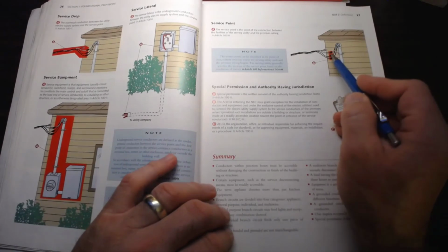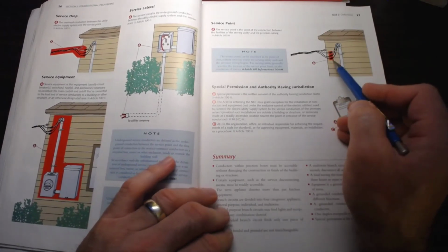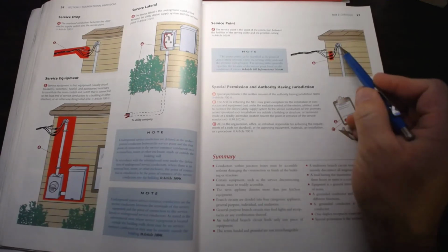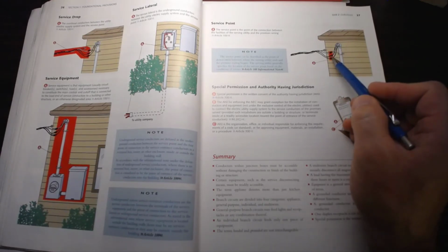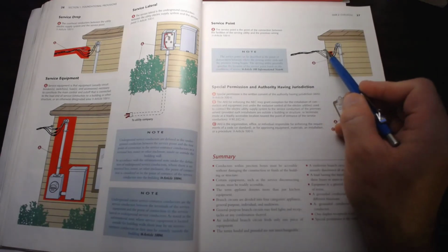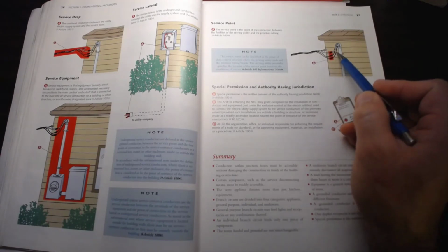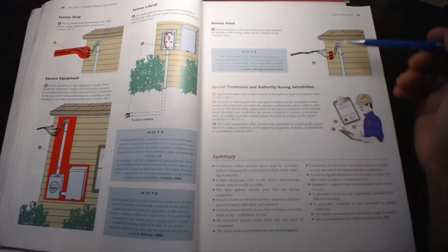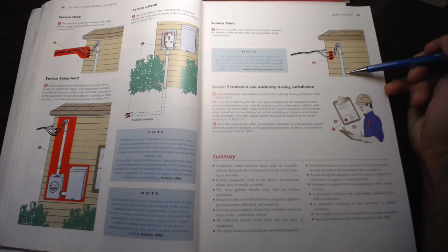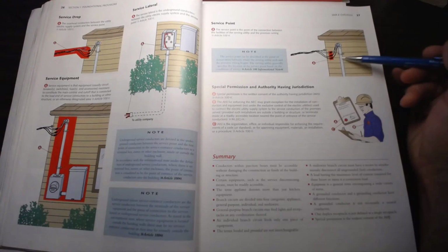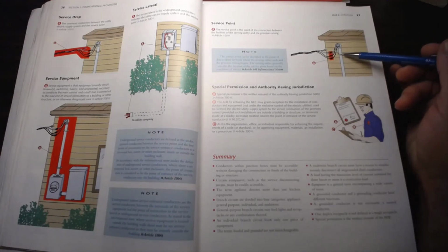The service point is the point in which the utility connects, and it's at that location is where you're going to usually see the disconnect or the change of ownership between the customer and the utility. So could the utility wire fall off and rip the riser down? Yes. In some utilities, that riser replacement and conductor replacement would be on the owner, and the utility would change out the conductor. So again, it's utility by utility or municipality.